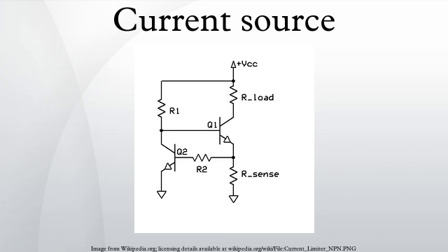The voltage follower adjusts its output current IOUT flowing through the load so as to make the voltage drop VR equals IOUT R across the current sensing resistor R equal to the constant input voltage VIN. Thus the voltage stabilizer keeps up a constant voltage drop across a constant resistor. So, a constant current IOUT equals VR/R equals VIN/R flows through the resistor and respectively through the load.